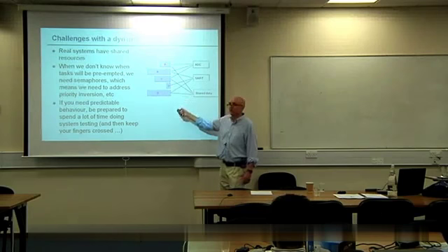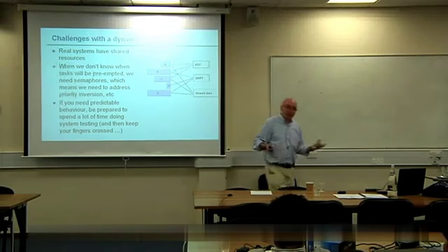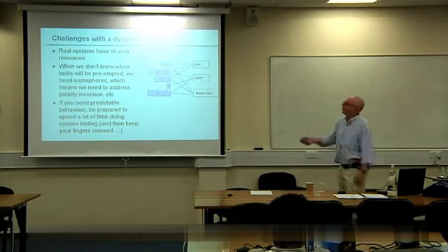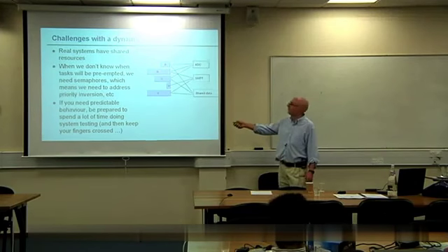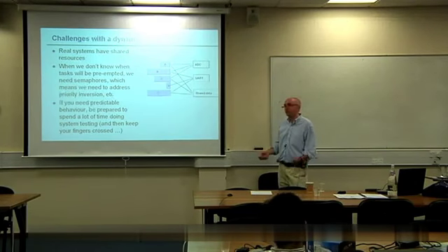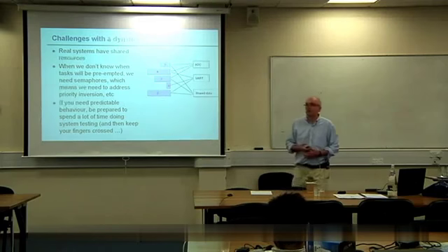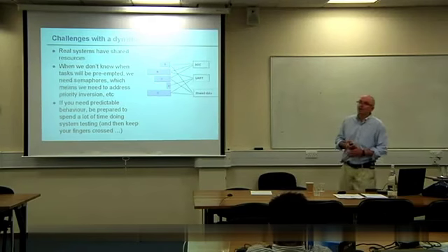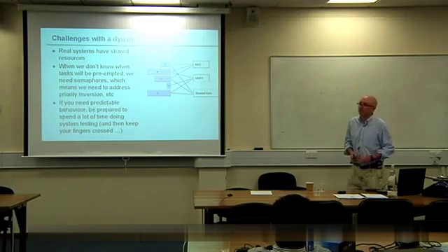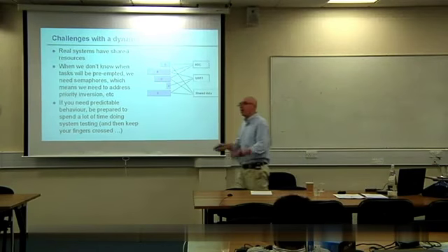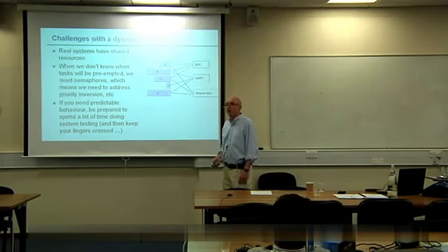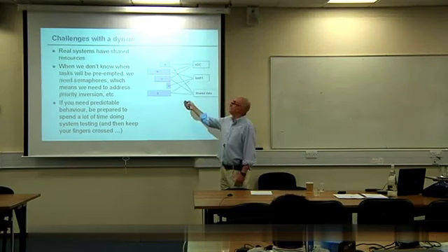What happens is these tasks might be linked to a serial interrupt, a CAN interrupt, a timer interrupt, various forms of interrupt which happen at non-deterministic times. And if that's how your system has been constructed, then there's no way for you to say, you don't know when A is going to run next.